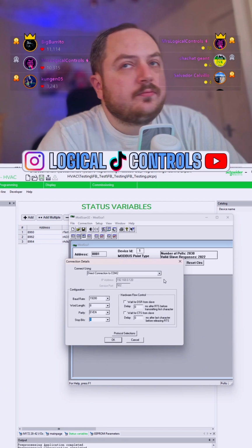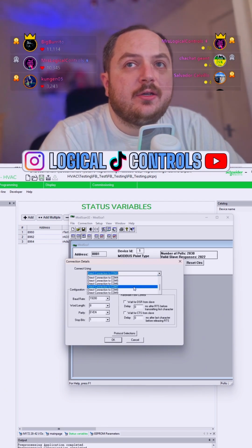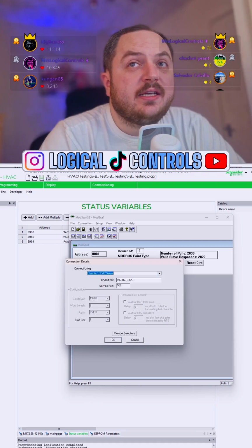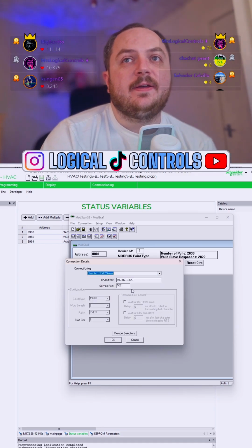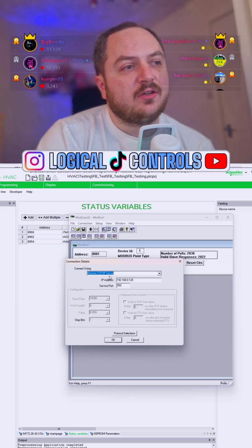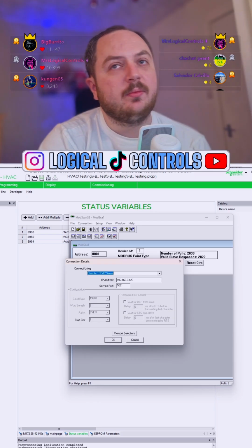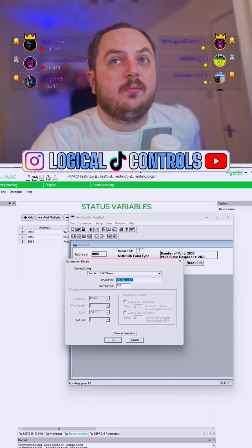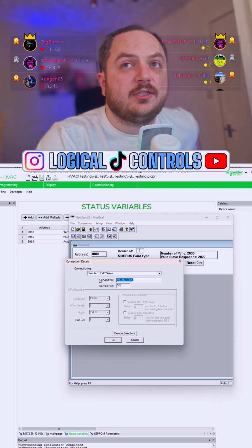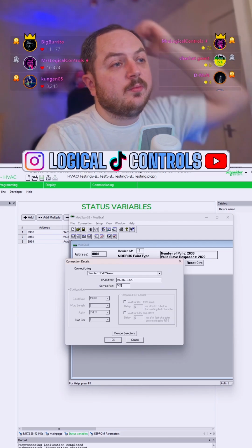Yeah. But between Modbus TCP and RTU, I never used ASCII. ASCII, I've never ever used that. That's kind of old school. ASCII got replaced by RTU pretty much, and RTU still does exist, but I'd always prefer Modbus TCP. Like I say, it makes it super easy. You need an IP address, the port number as well, which is always 502 for Modbus.